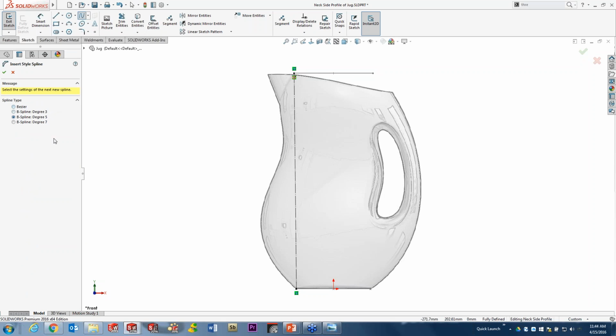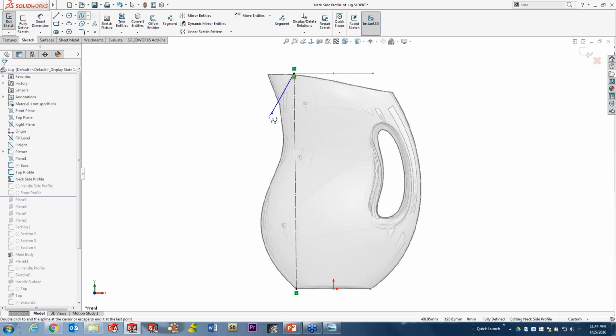And that's always been one of the flaws of a Bezier curve, and input handles that you can change the inflection, direction, angle of attack, and weighting. This is a lot better method. So the way we do this now with the style spline is we use some construction geometry as the input. So I'm just going to go ahead and click and release. We'll move over here, and I'm just using my preview a little bit to follow this, but I'm actually going to change this quite a bit as we get going.